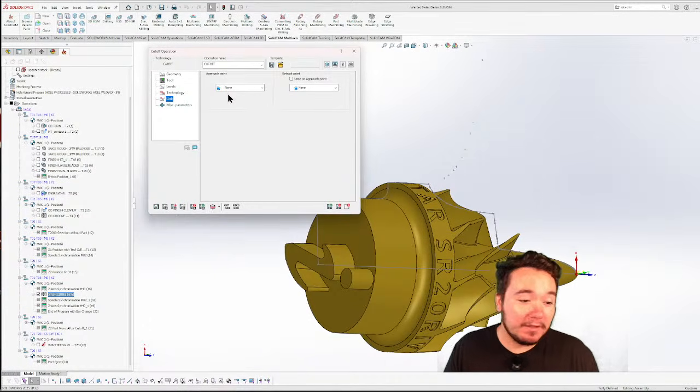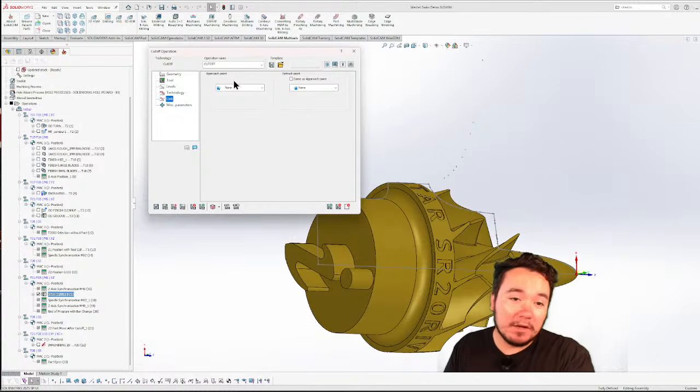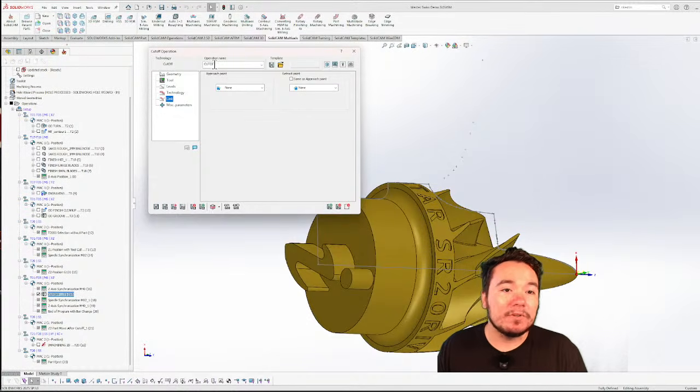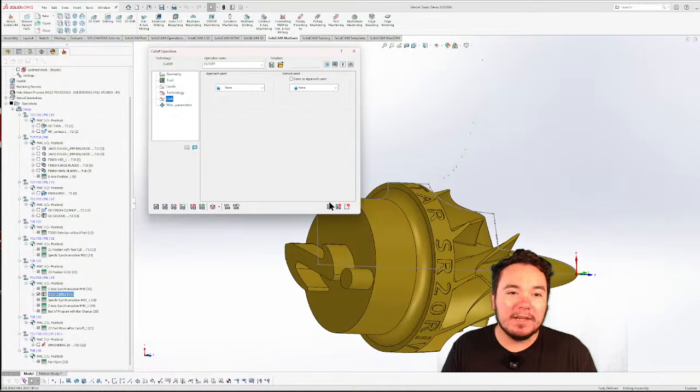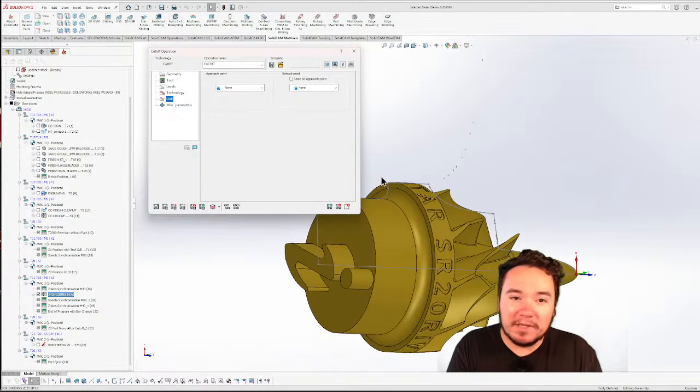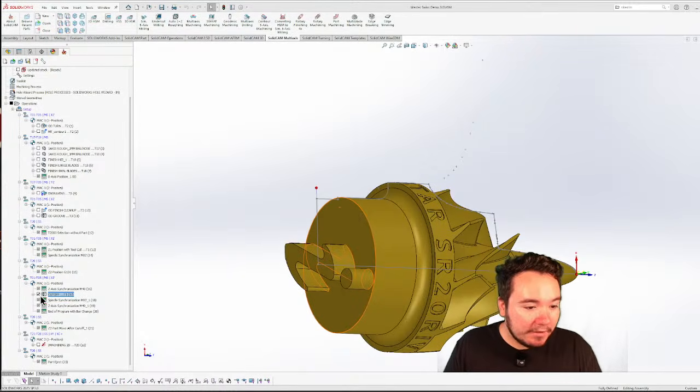For this one, you have to do no approach points or none when you're selecting that in the link page. Just a thing that you have to do because it's already set up, so you don't want Z-axis trying to pull it anyway. So it's already ready to go. It's at the X position, it's at the Z position, it needs to cut out, and then boom, you just cut it. It might move just a little bit depending on if you measure everything correctly. But from there, you're good to go.